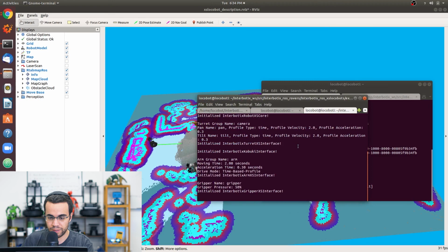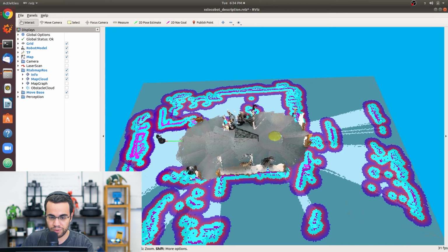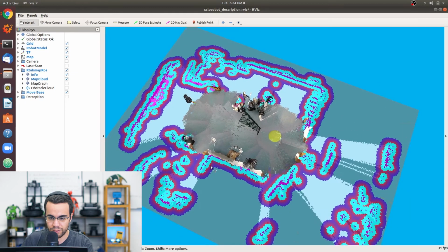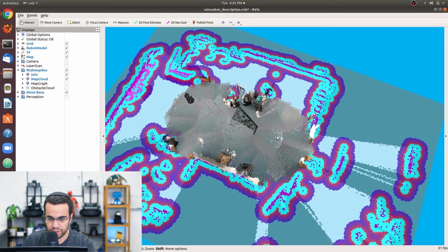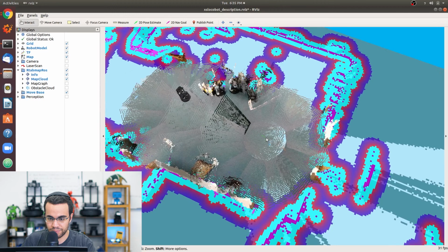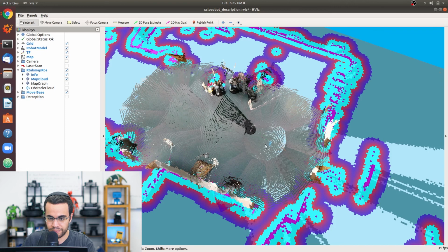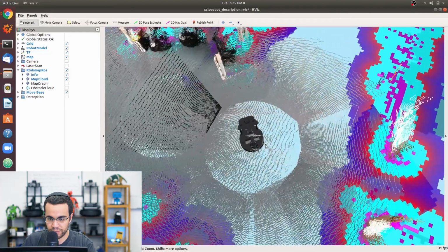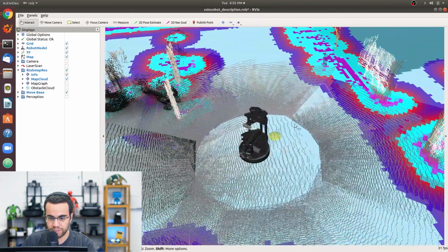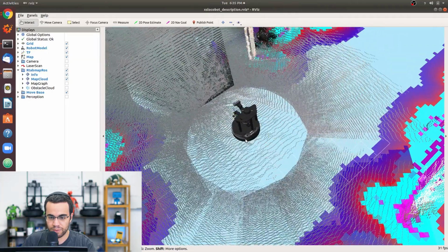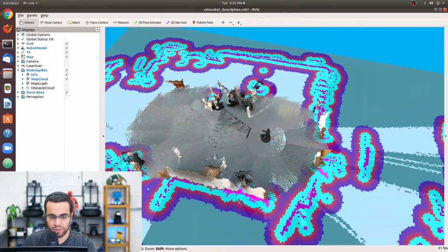It should start an instance of it, and should actually start moving there. And we started, it was around here somewhere. So hopefully the LoCoBot should end up in the middle of this circle, facing that way. And it should rotate. Perfect. So that's two other ways you can navigate with the LoCoBot, either using the Nav Goal tool in Rviz or using the Python API.